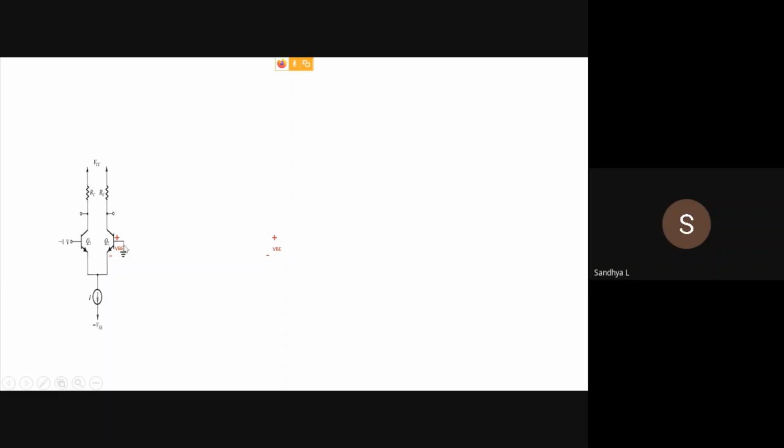So normally we say that both the transistors should be off. But when these two transistors are part of a differential amplifier, the difference is taken and the difference is 1 volt. When you are taking the difference, you take the modulus. You don't take this minus this, you take the modulus. So modulus of minus 1 minus 0. So difference is 1 volt.